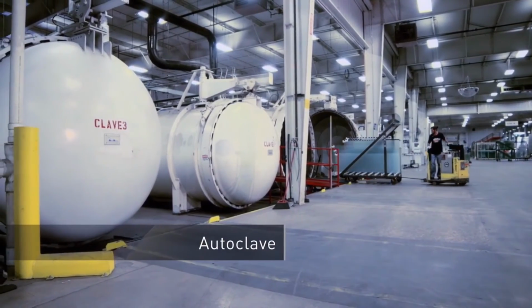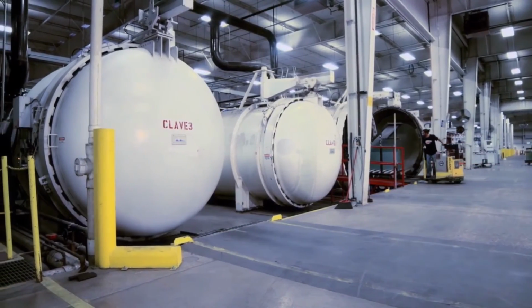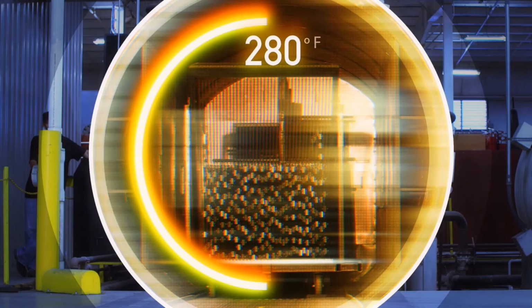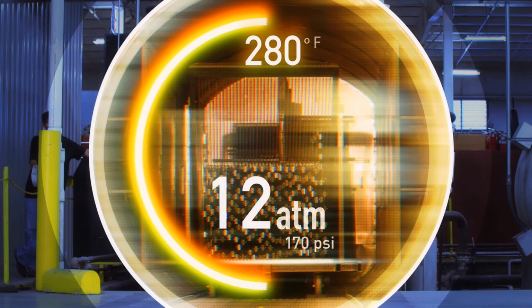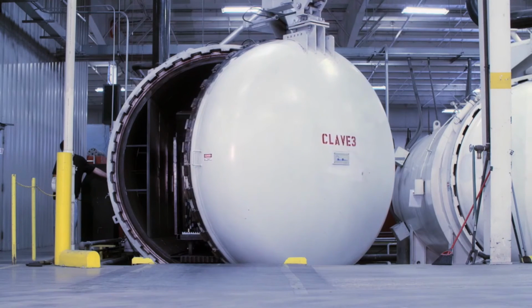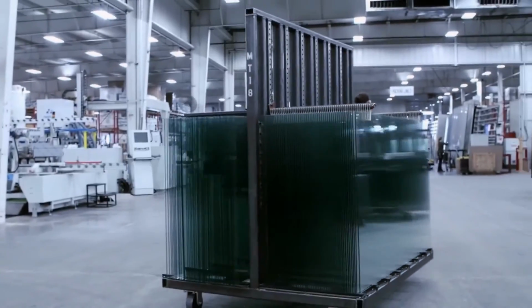And the laminated glass enters the autoclave chamber. The autoclave is at 280 degrees Fahrenheit and more than 12 times atmospheric pressure for 2 hours. The autoclave finalizes the interlayer addition to the glass, and the product comes out clear.